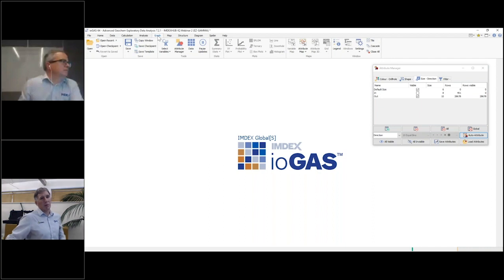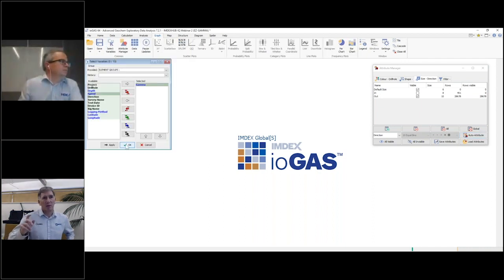Probably worth saying at that point, Fred, in deploying the gamma tool, you can certainly run an in and an out survey, get the driller to run an in and out survey as a way of doing QA. If you're on longer holes, or you're pretty comfortable with the deployment method and you think everything's working pretty well, you can just drop the tool down pretty quick and then pull it out slow, which is probably the best way to do this if you want to cut down on survey time.